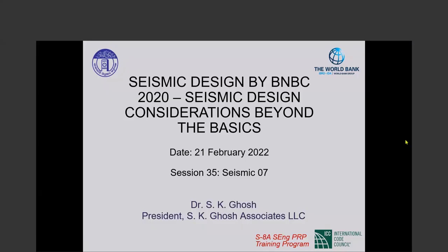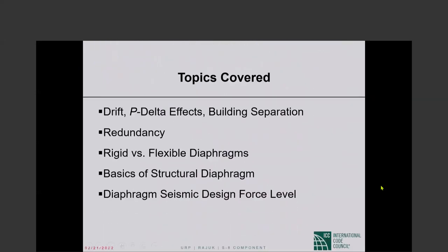Everybody. Today's session, as you see, I titled Seismic Design Considerations Beyond the Basics. That is the most descriptive title that I could come up with for what I have in mind to discuss today. These are the topics. First of all, drift, P delta effects, building separation. Drift, we have discussed to quite a significant extent. The other things we have not. Redundancy, rigid versus flexible diaphragms, basics of structural diaphragms, and diaphragm seismic design force level.